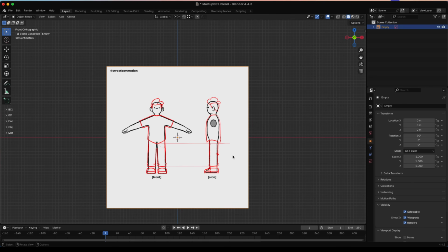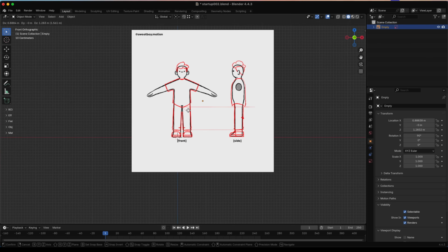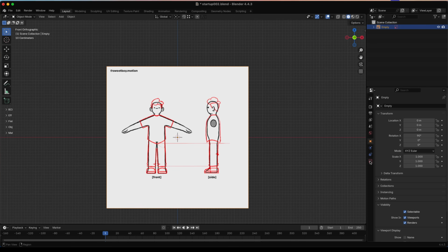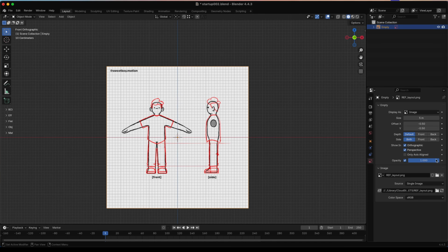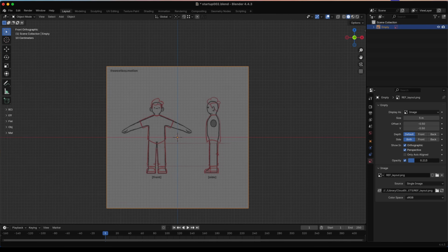So once we brought that in, that works pretty good, but don't go trying to line it up with the origin point quite yet. We're going to make some tweaks to the image itself so that it actually lines up and improves the quality of life in Blender. So the first thing we're going to do is go over to the properties panel here. It'll look like a classic motel art painting here with the mountain and the sun. And we're going to tick on opacity just like that.